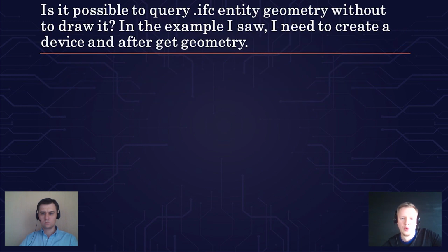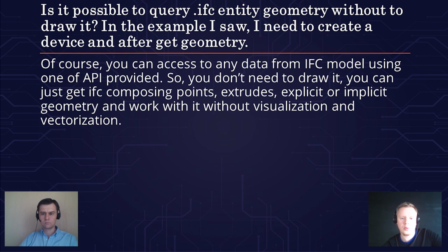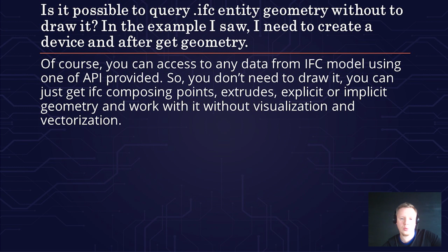The next question, is it possible to query IFC entity geometry without drawing it? In the example that I saw, I need to create a device and after that get geometry. Of course, you can access any data from the IFC model using one of the provided APIs. So you don't need to draw it. You can just get IFC Cartesian points, extrudes, explicit or implicit geometry, and work with it without visualization and vectorization.